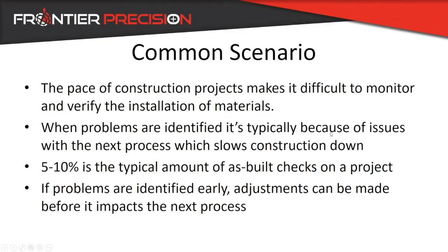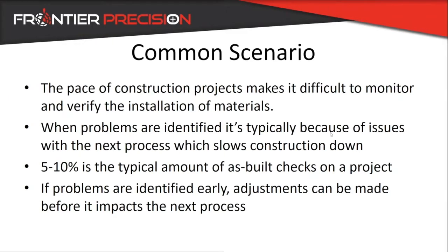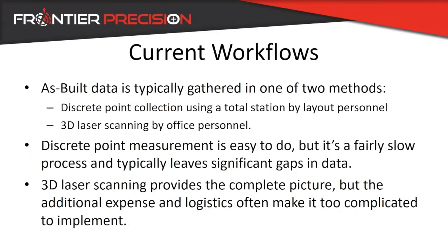Currently, the way that as-built data is collected is really one of two methods. It's going to be either a discrete point collection using a total station. Typically nowadays people are running robotics, but conventionals will do it too.